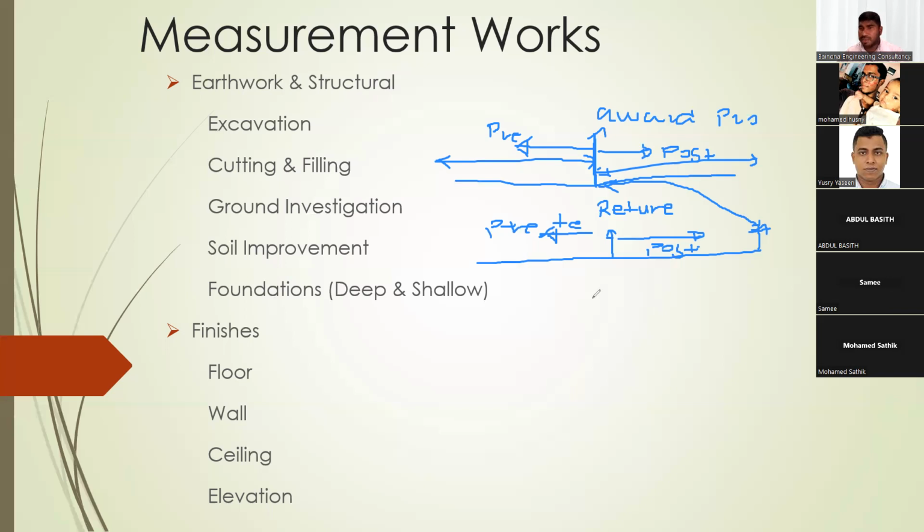So I'm just lining up the engineers' duties, the quantity surveyors' duties who work with the consultant. Then you prepare a report, and then you suggest the contractor to the client. You recommend he is the best guy to go ahead. Even the recommendation you must give by doing so many analyses. Not only a commercial analysis, you must know how technically competent this guy is. Based on the technical score, you have to visit the site and check the quality of the work. Then financially, whether he's capable or not. Financial capability has to be checked.